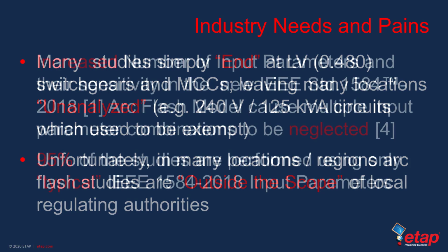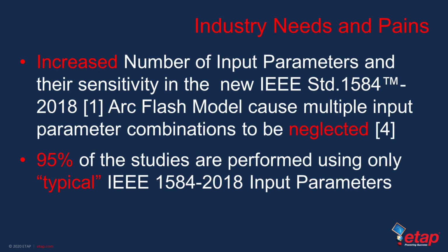Well, that is one of the main purposes of this concept of the C areas and also the arc flash auto evaluation tool. Furthermore, after spending several years of my life working on the development and validation of the new IEEE 1584-2018 arc flash model, it became apparent that our current methods of analyzing the results were sort of inadequate. The enhanced sensitivity of the new model to each input variable and the increased number of variables required modern tools which can help us analyze hundreds if not thousands of possible combinations of these input parameters.